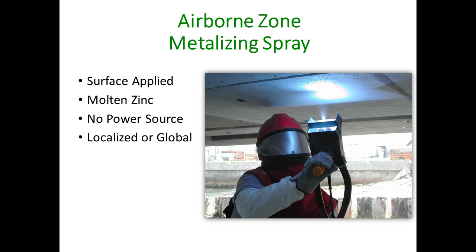And then another area, this is popular. Florida DOT does a lot of this. It works really well, and it's a fairly easy solution, and that is metalizing. It's a metalizing spray, and what this is, it's a surface applied molten zinc that's basically sprayed or blown onto the surface of the concrete. So it's a surface applied galvanic anode.